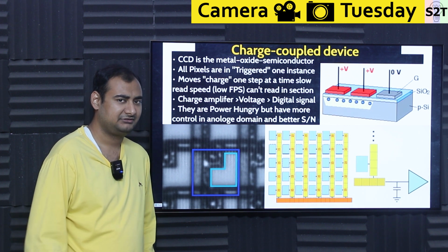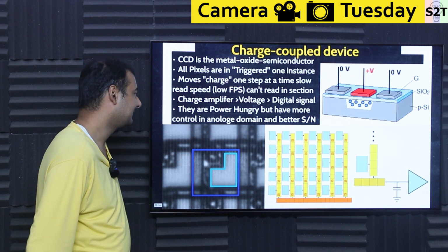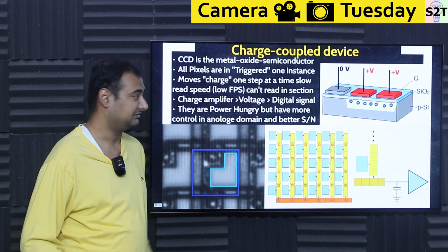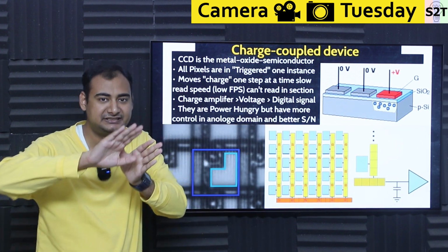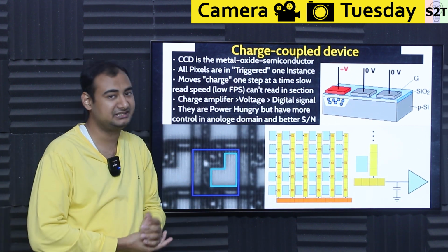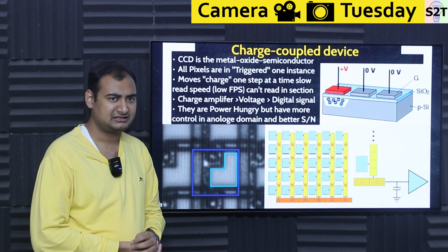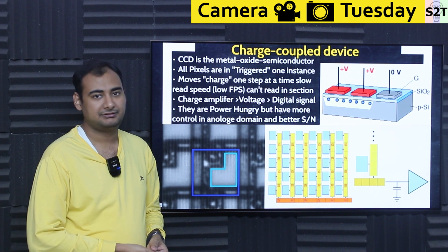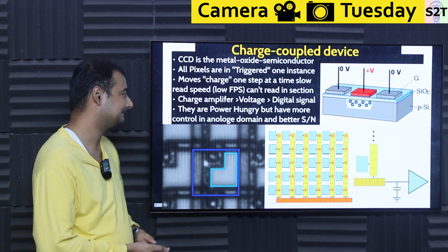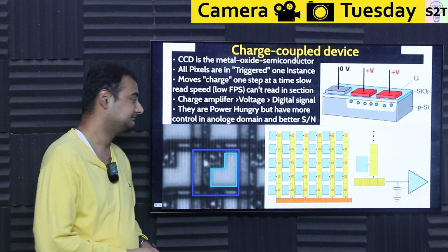And I'm genuinely shocked that we figured this puppy out in the 1980s. However, this is a power hungry step. You can see that it's shifting charges brick by brick. It's fundamentally energy consumption. So that's why in early 2000s digital cameras, even though they were using CCD, they were so brutal on batteries. Fundamentally, it's a power hungry system.